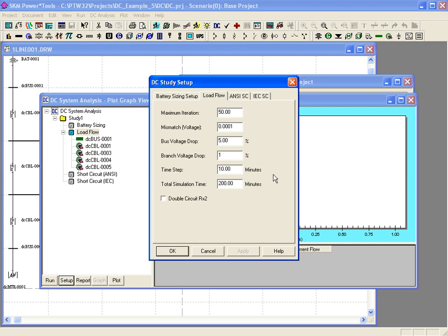The most important option is the duration of the time step. The choice depends on the need of a particular study. For a system with loads that change over a period of several hours, it may be appropriate to use a time step such as 10 minutes. Conversely, if the important part of the study is the few seconds needed for backup generation to be started and loaded, the appropriate time step duration may be 0.01 minute. For our example, a time step of 1 minute is appropriate.